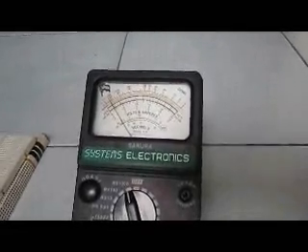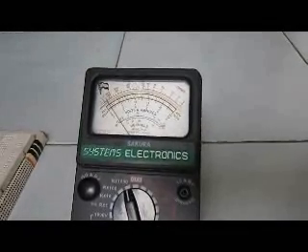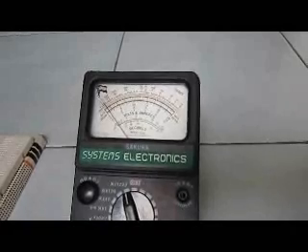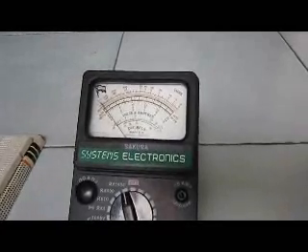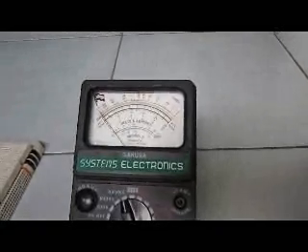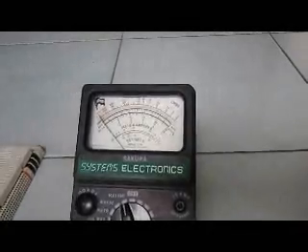On connecting the capacitor, the small battery in the multimeter charges the specimen and gives an indication of charging current. The charging current gradually decreases, tending towards zero value within about 40 seconds.